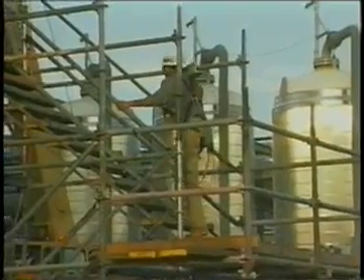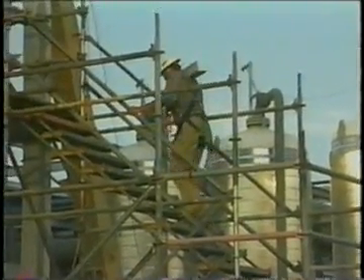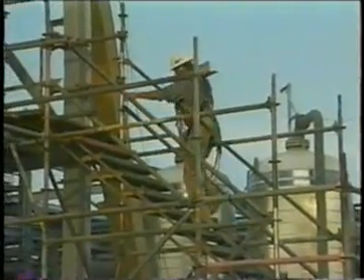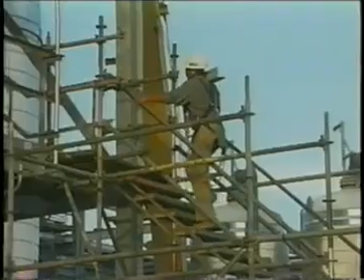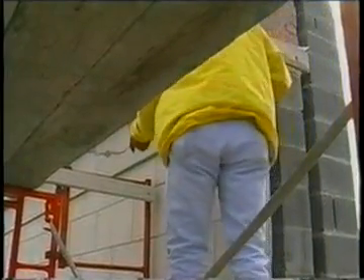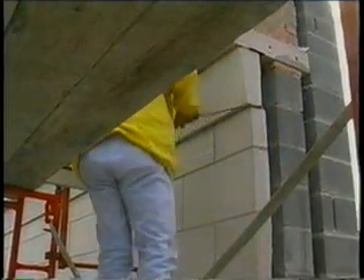When the platform is more than 2 feet above or below a point of access, there must be a ramp or walkway or direct access from another scaffold, structure, personnel hoist, or similar surface. On suspension scaffolds, the competent person must check the scaffold support devices, tiebacks, hoisting equipment, and connections for proper strength and to prevent swaying.